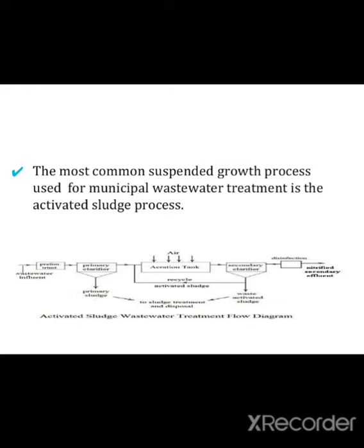This is known as activated sludge. The sludge is recycled back again and again till the sludge percentage gets decreased. And finally, the treated water is supplied to the tertiary treatment and the water gets treated.